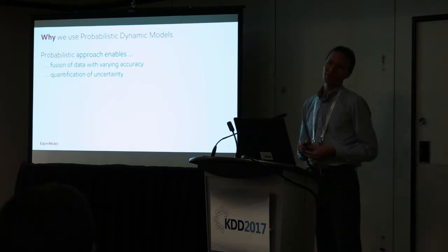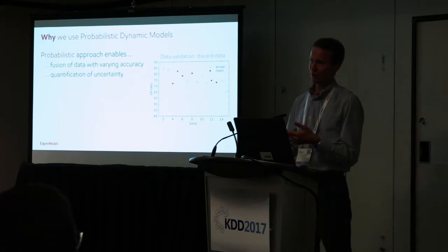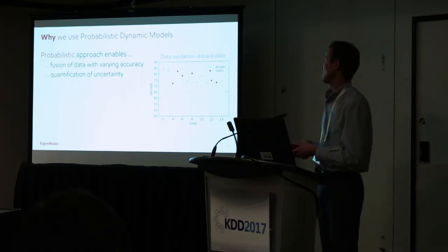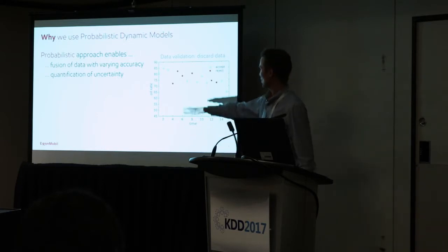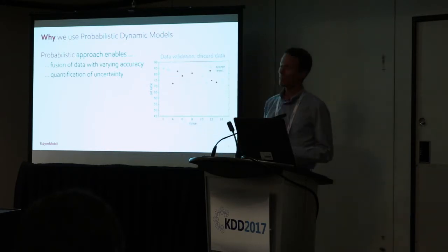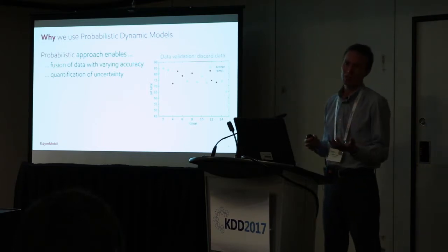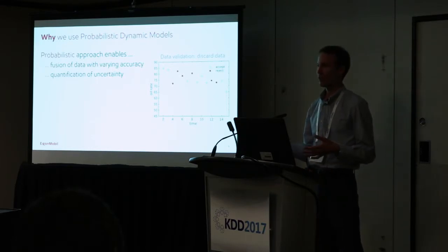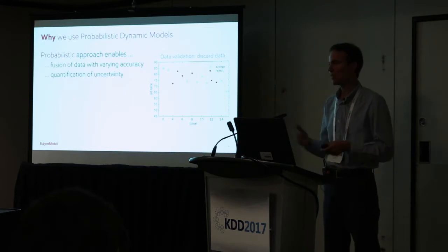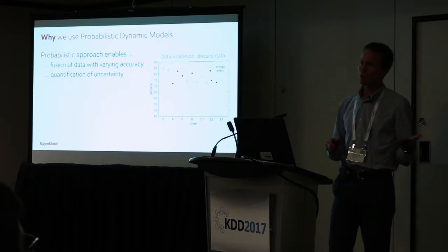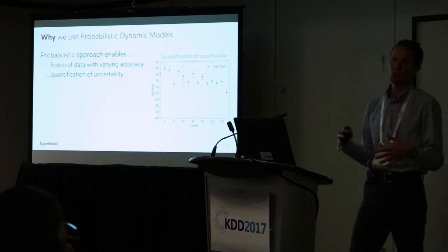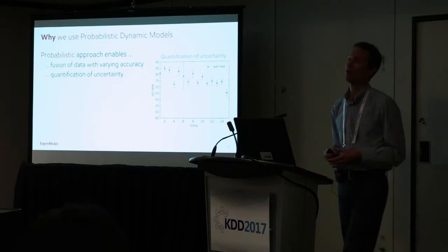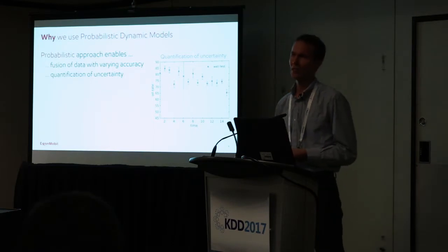So the way we explain it to them is like this. The way they typically do it now is with a more black and white approach. There are ways to validate if a measurement is good or bad. What you're looking at here, and I will show several of this kind of plots, is the oil rate as a function of time. Looking at these metrics, say if a sensor has clearly failed or not, you either accept the measurement and use it, or you reject it and just discard it. What's bad about this approach, of course, is that you're really losing data that you still might be able to use. When we instead use uncertainty, we can salvage a lot of the data. We can basically use almost all of the data. Some need to be totally rejected, but typically we can still use more data. So this will lead to more accurate results in the end.